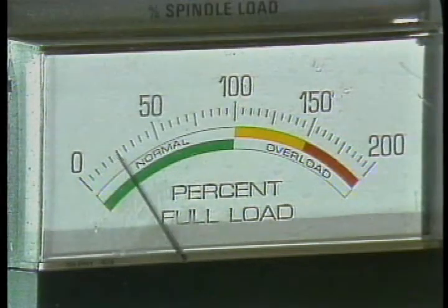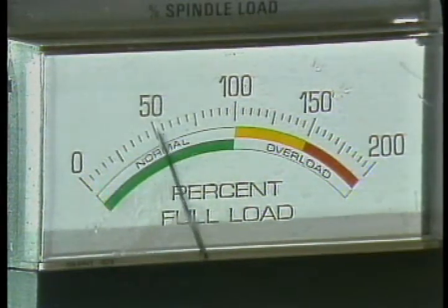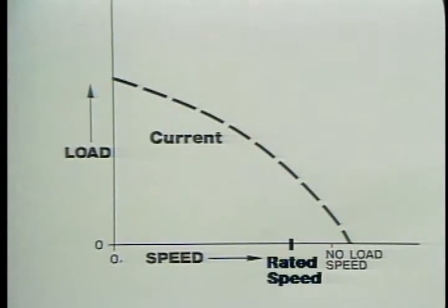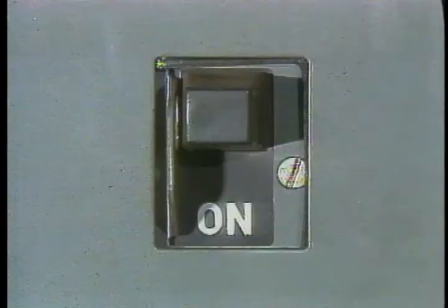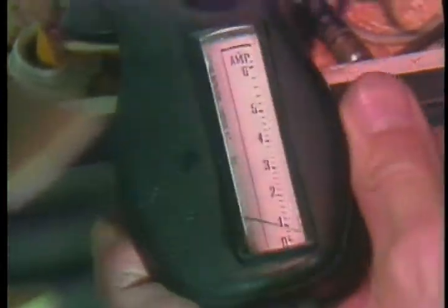That means that most motors can start and run under overload conditions. However, they will not reach rated speed, and that could be damaging, because below rated speed, a motor is drawing too much current. If it is stalled or runs too slowly for too long, it will overheat, and the insulation will be damaged. The overload breakers are supposed to protect the motor by tripping, but do not rely on them completely. If you suspect that a motor is overloaded, check its speed or the current to it.